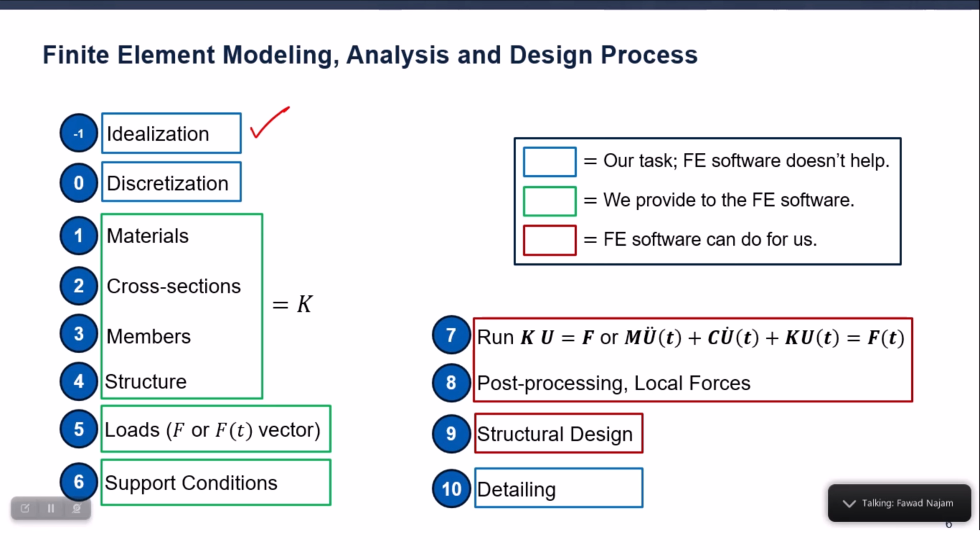So, when you are given the trial drawings, you should idealize which components in that structure to be built in future need to be idealized with which component in the program, right. Each of the structural analysis programs offers you an inventory of elements, like the frame element I showed you in one example, but there can be 2 dimensional elements or 3 dimensional elements also.